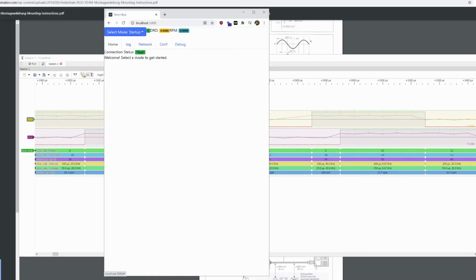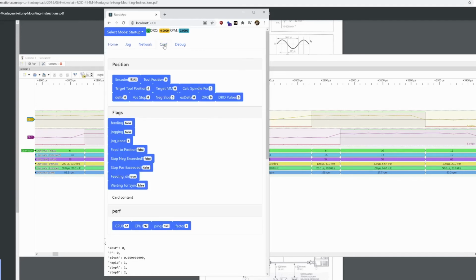This is the user interface for my electronic lead screw project, and in the configuration here, I actually have the ESP32 updating the encoder counts over WebSockets to a web interface, which is actually pretty cool. So I have this hooked up to the ESP32, and as I rotate the encoder, that's about a half of a turn, you can see the signal update.